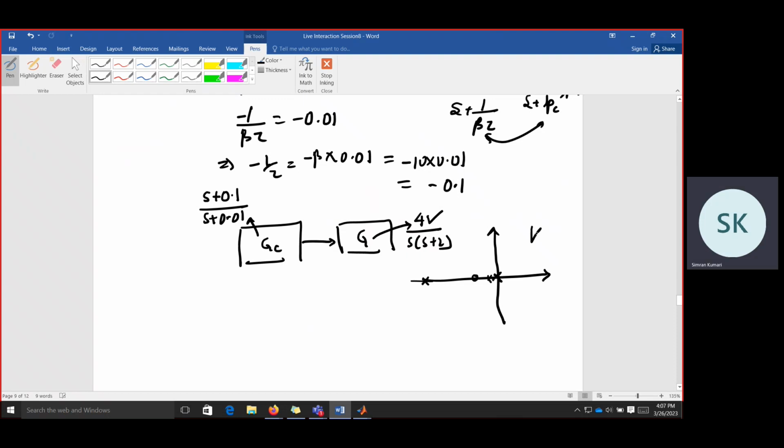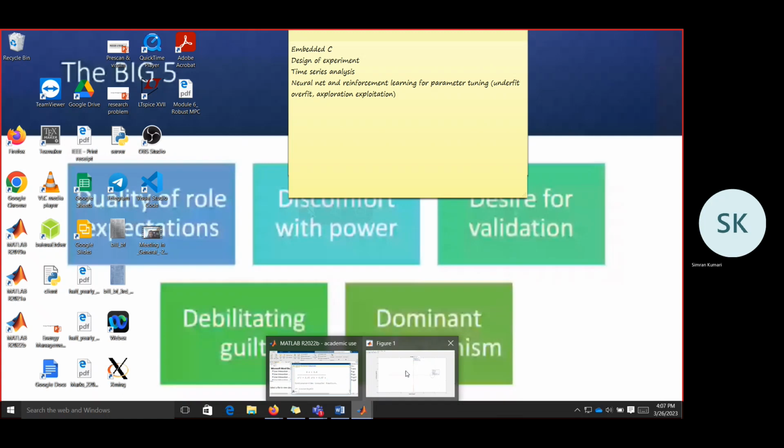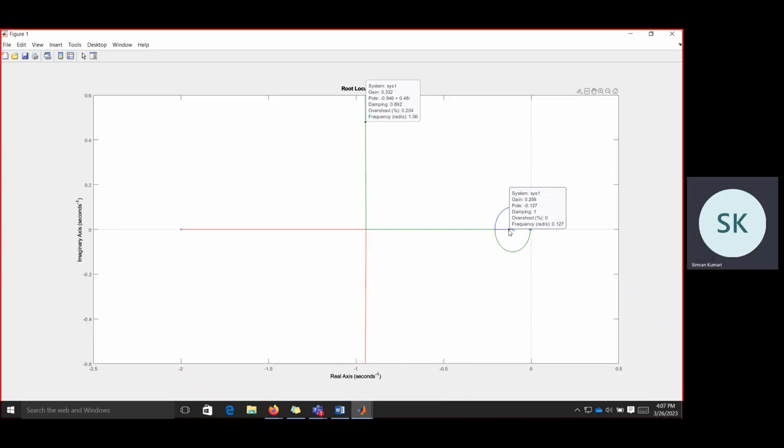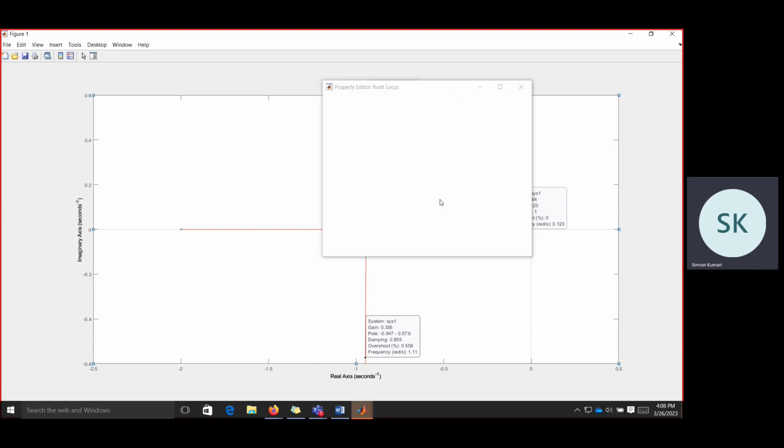What we'll see for k equal to 1 only is the location of poles, and from there you can see one of the poles is very close to 0. This is another pole. Let's see. This is going towards this. Okay, fine. This is the closed loop pole that we found earlier, which was -1 plus √3 j. So at gain k equal to 1, it should be equal to that one only.